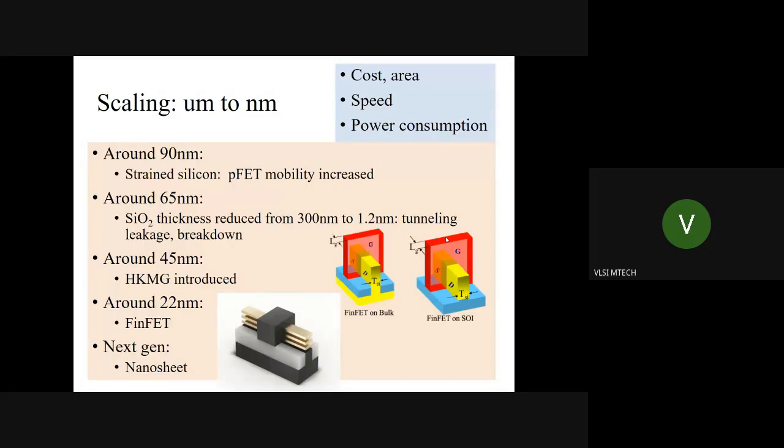Because the physical oxide thickness is much thicker, there's less chance of breakdown and leakage, while since the permittivity is high, it allows a lot of field to flow through it, and I do not lose out on the control that I get from a thin oxide film.